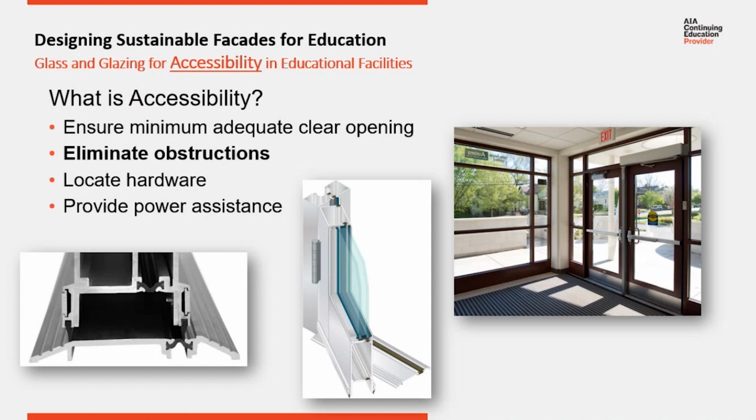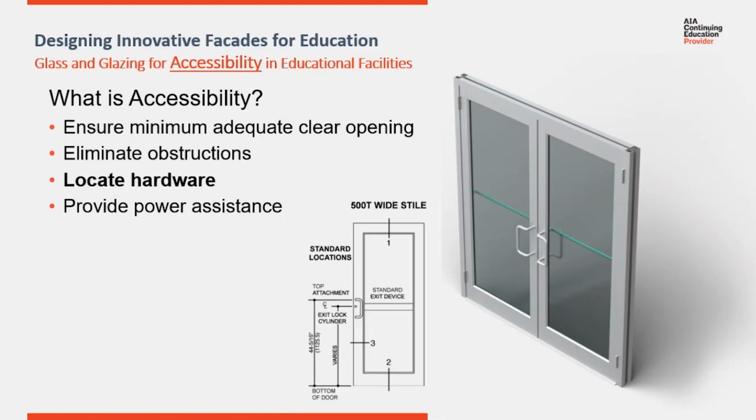Improperly applied or adjusted door hardware can also create a barrier to accessibility. For example, a door that requires excessive opening force or that does not allow adequate time to safely pass through it would be considered a barrier. ADA establishes maximum heights for hardware location, key hardware components. The heights are limited based on what someone can reach from a wheelchair. Most all manufacturers have made ADA prescribed hardware locations their standard application. It is safe to assume that when you install aluminum commercial entrances, the locks, push, and pull locations are all going to conform with ADA requirements.